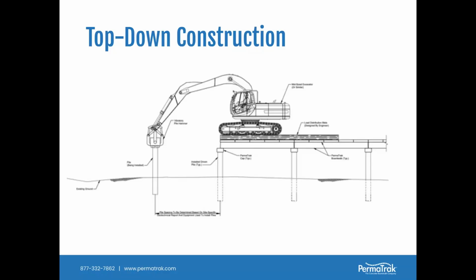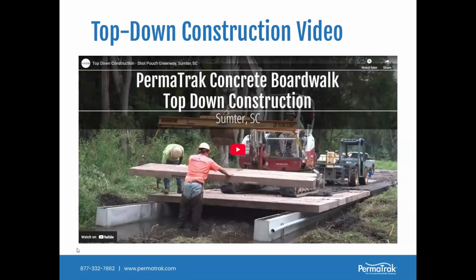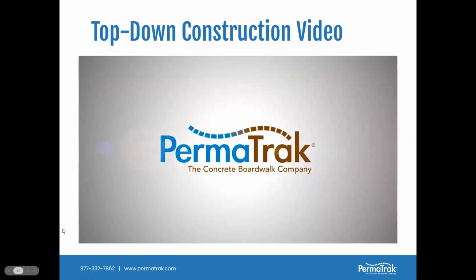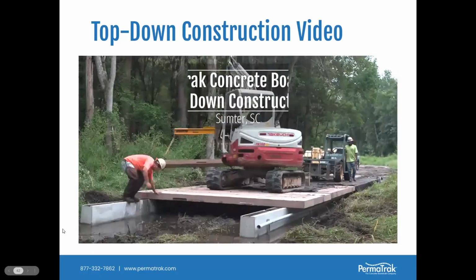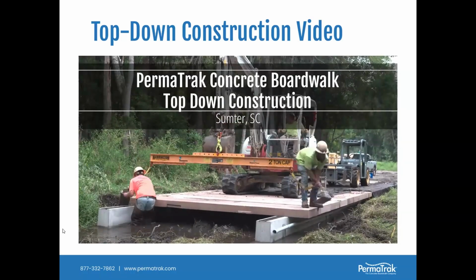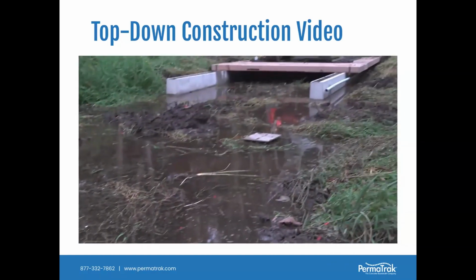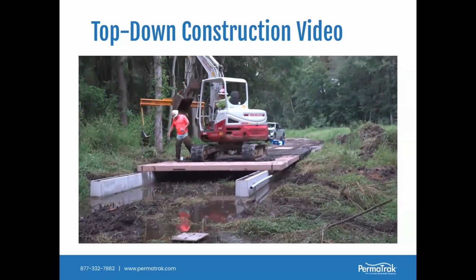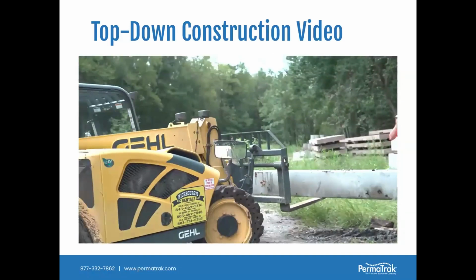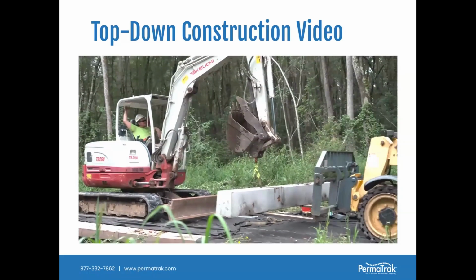We do have some resources on our website. We have a number of articles that take you through top-down construction, and a couple of different videos. I'll show you just a quick couple of seconds of a video to show, again, visually what a top-down looks like. In this case, it was partial top-down. They installed all the helical piers, went in and as-built surveyed those piers, and gave us the survey results. We checked our beam layout, adjusted it as we needed, and then they installed all the precast from the top.